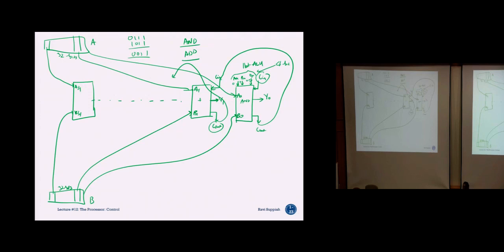So for an add operation, for example, the total time that it takes would be the time of each ALU multiplied by 32, correct? Because I need to wait for all 32 bits to be completed before the final carry out is generated, and the final Y31 is generated. So that is the idea of the 1-bit ALU.